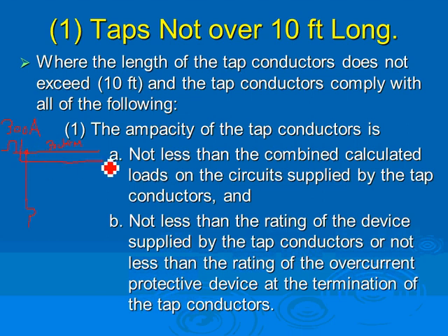Now remember, this is inside a gutter. And I'm going to make 2 taps. Tap number 1 is 10 feet and tap number 2 is 25 feet. So I'm just going to say 25 feet here and this is 10 feet. These are the most notoriously famous 2 taps that we guys use. You have a 300 amp feeder, you pull a 300 kcmil conductor, put it in a gutter. I call the taps the poor man's job, because I'm an engineer, I don't pay for the equipment, I design them, so the rest of you guys have to bend them and pay for them.